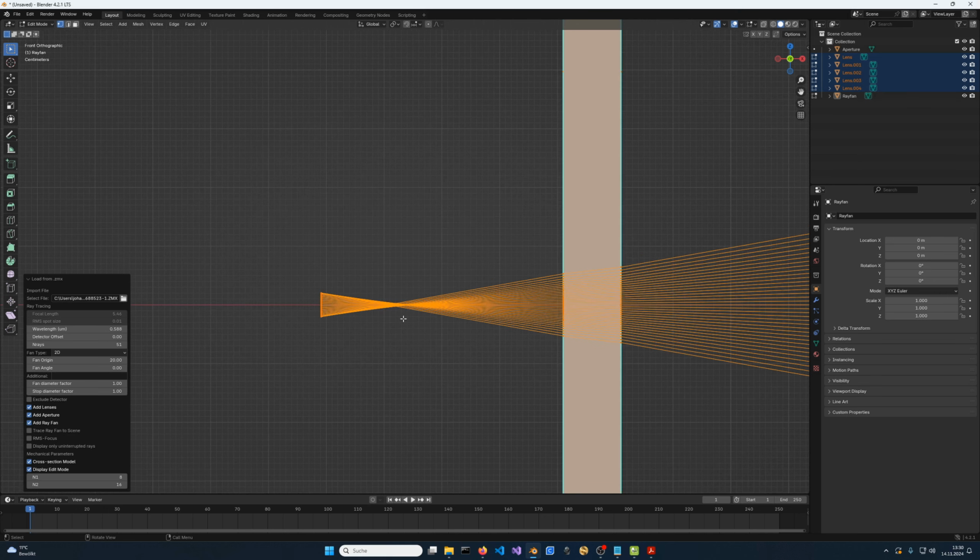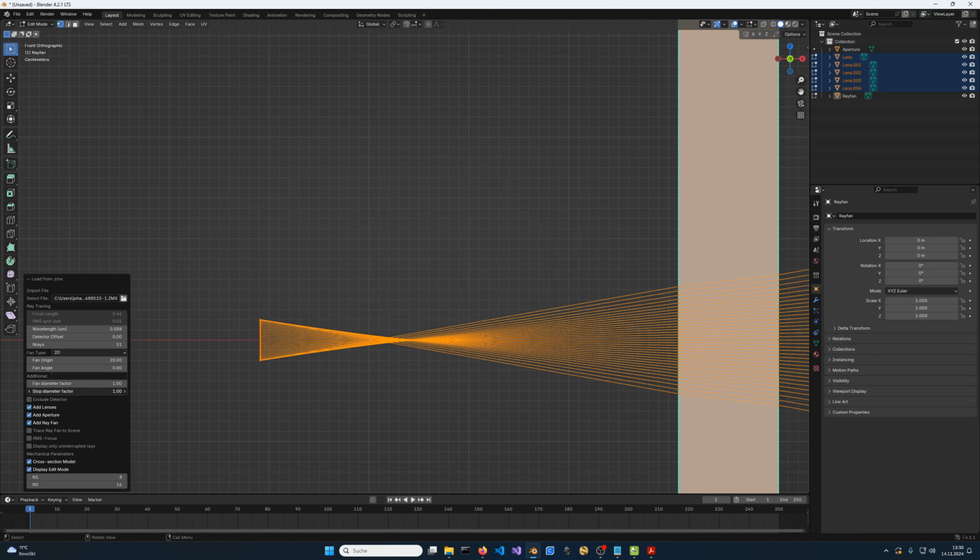However, if we do the same sort of inspection for this lens by stopping down, we can see that actually the focus gets even worse. So it doesn't seem like the paraxial back focus is a good match to this image location that is indicated in the zmx file. So obviously for this lens, that is not the issue.